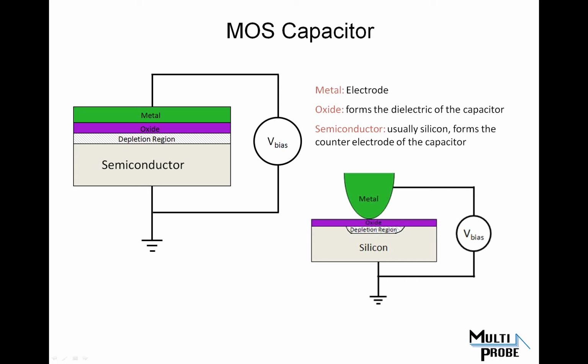Well, now it turns out that with capacitance voltage spectroscopy at contact level, the left picture is more like the actual picture. In other words, there is a fully defined metal or polysilicon, although I guess it's metal now, gate structure over some oxide. And so the fringing field effects are going to be the field effects inside of the device itself. So it makes for a nice simplified structure to understand.